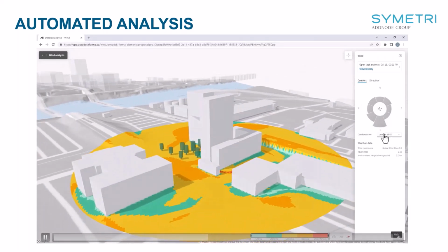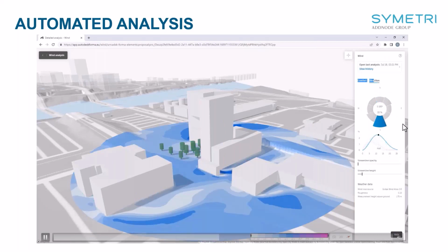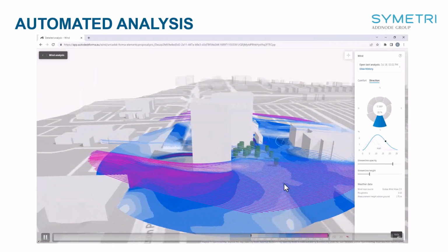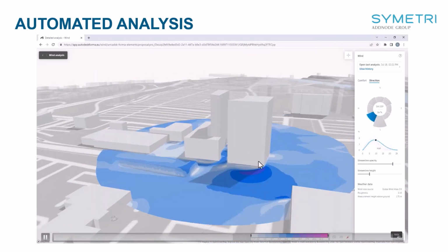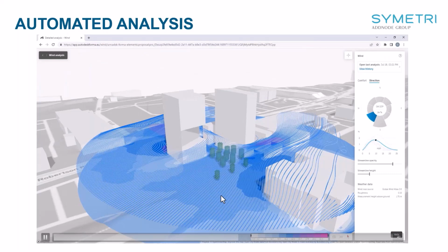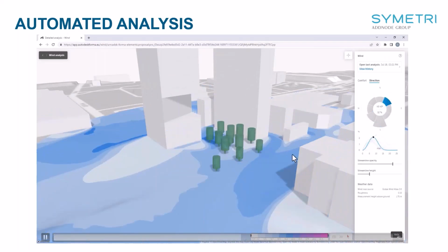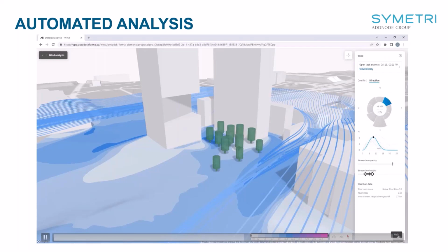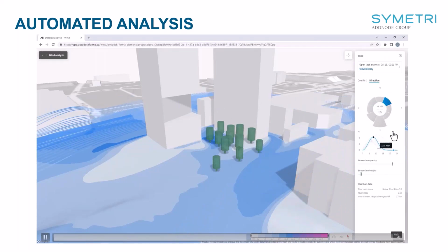Here, what we're looking at is the detailed analysis, in which, again, you can pick your comfort metrics, whichever one is required, and look at comfort or even direction overlaid with wind speed. So again, if we turn on the streamlines and turn up the speed, we will start to see actual streamlines and actual CFD effects of the site itself. Again, this could make or break a design. How many times have you been on a site where wind shears are way too high? There was no real way of determining that. Now we have the ability to do that within 20 minutes of me starting this presentation.